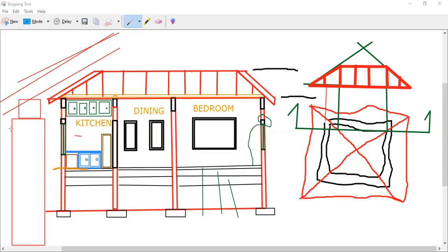To determine exactly how far this is supposed to go and to establish your overhang is not so difficult. You can draw a line here, draw a line here. Let's use a different color, say, green. Well, I could offset this wall out 450, to have it out here. And then you would trim off the excess out here, to clean it up to look just like this end. And then you would proceed.